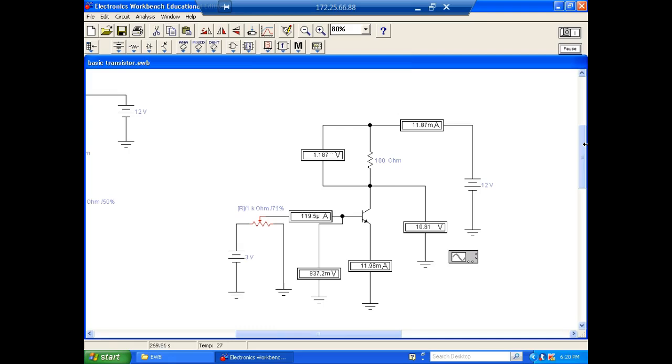So we're operating it like a rheostat now, right? You understand. But what am I controlling the resistance between here and here with? I'm controlling it with this base current. So as I raise the base current up, the resistance between the collector and the emitter is going down. So we've got 9 volts across the transistor. We'll go up and put it in saturation in a minute.